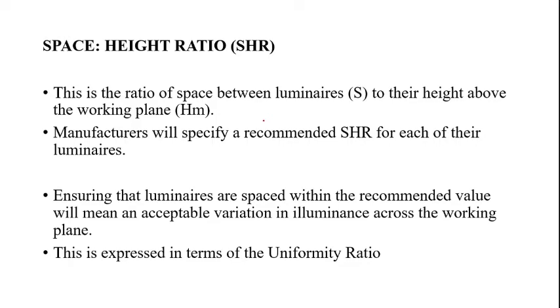Specifying a recommended space to height ratio ensures that luminaires spaced within the recommended value will give an acceptable variation in illuminance across the working plane, so that an acceptable variation in the illumination on the working plane is obtained.